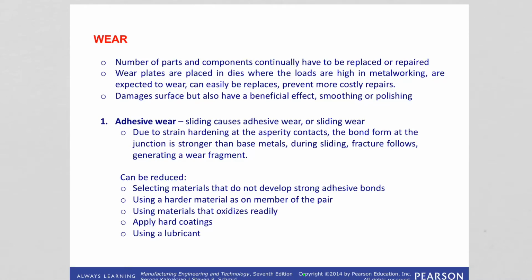So how can we reduce adhesive wear? You can do one or more of the following. Select materials that do not develop strong adhesive bonds. You need to be careful because these can be two different materials, so select materials that do not form strong adhesive bonds.